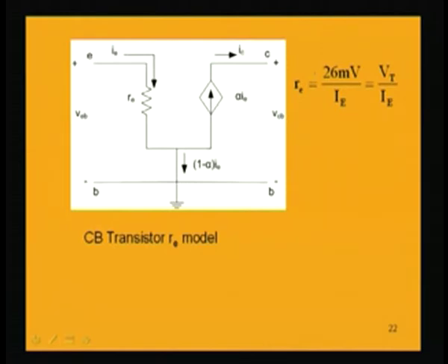transistor. So, now if we again redraw the circuit, in place of this forward bias diode, we will be replacing it by this Re, and the other part being the same. So, this is the Re model for the common base transistor. Here the value of Re, the dynamic resistance, we can calculate for a particular biasing point, given the DC current in the emitter IE. If we substitute this term IE, then we get the value of Re, and that we will have to fit in. So, now we have the equivalent model for the common base transistor.